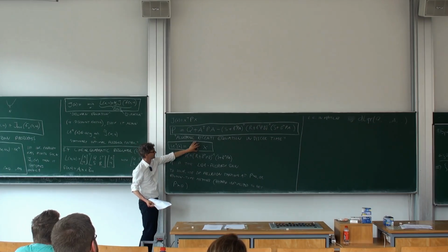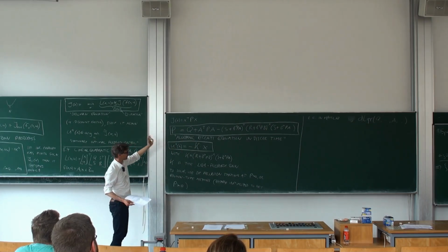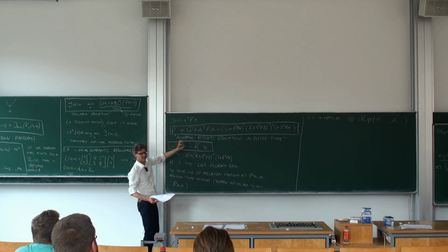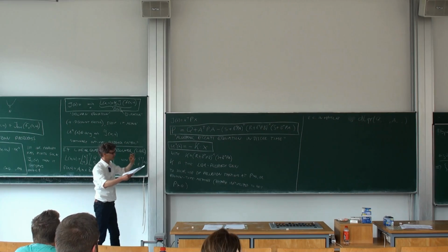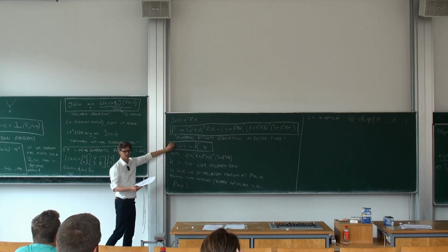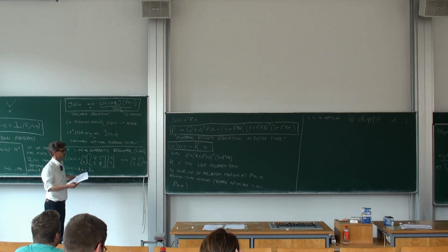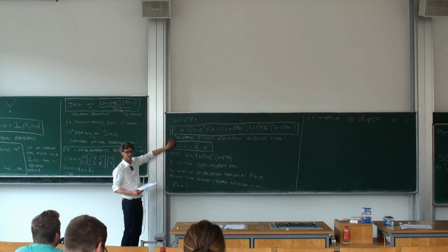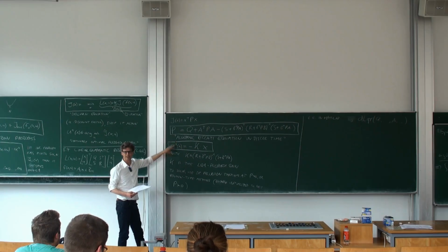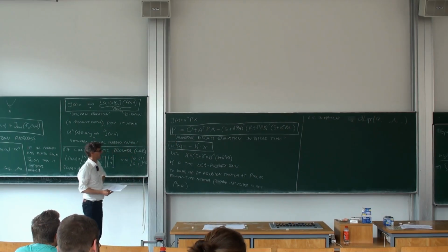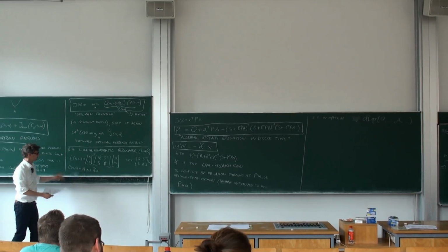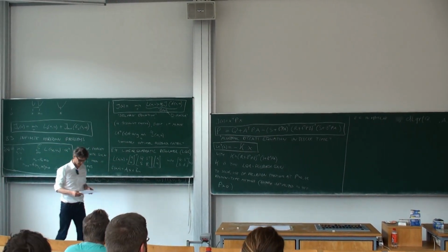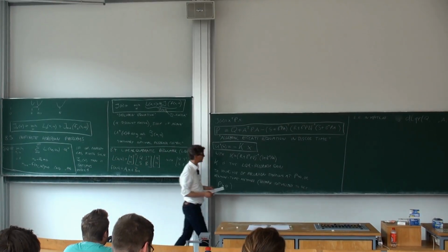At the end, if you have 5 states and 1 control, then this matrix K is just 5 numbers which linearly weight the states in order to give you the control. So it's an extremely simple algorithm to implement. Once you have found the matrix K, you have feedback that is optimal for this infinite horizon cost and for this linear system. So that's why LQR is so popular.